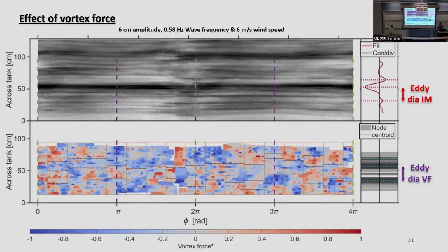Okay, then I'll go. For the structure function, what is your vector spacing? The vector spacing would be 5 centimeters. So how do you reckon, you're obviously missing scales in between those 5 centimeters. The smallest scale is probably on a fraction of a millimeter. How do you reckon that would affect the shape of the structure function? Well, the r to the power 2/3 law would stay as is. It's just that you'll fill the spots in between.